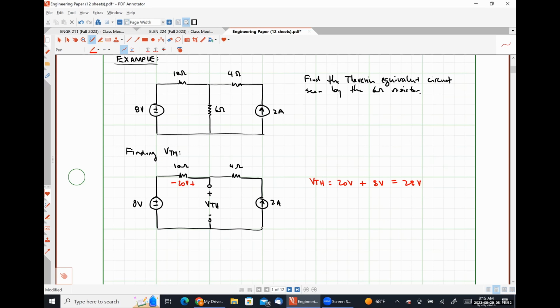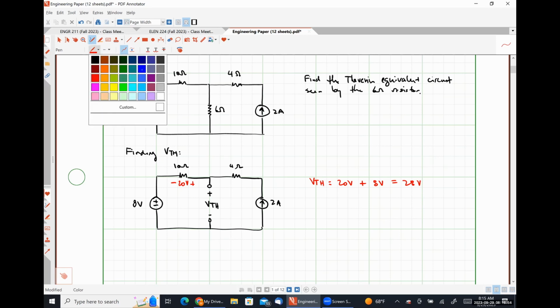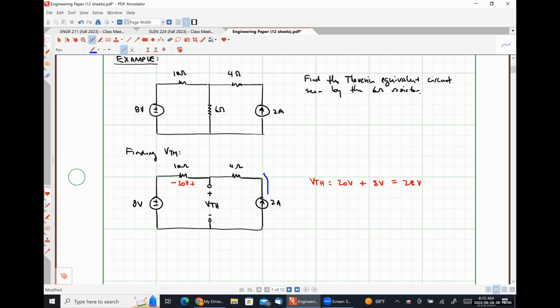All right, so this 2 amps of current is the only current flowing in this circuit. And so 2 amps times 10 ohms gives me 20 volts all day. And I have defined the positive polarity terminal such that the current was flowing into the positive polarity terminal so that I didn't have to use Ohm's law with a negative sign in it. Okay.